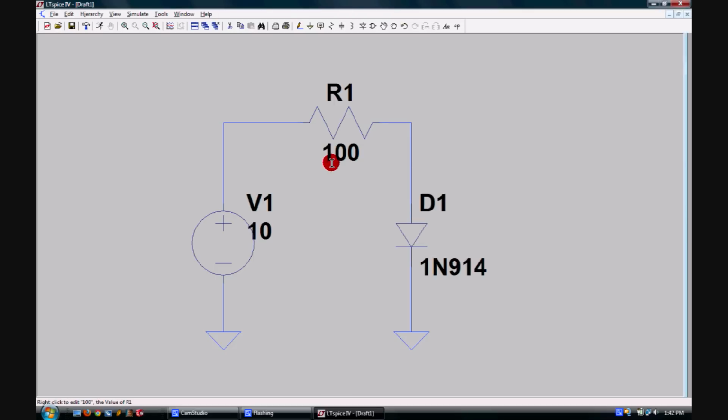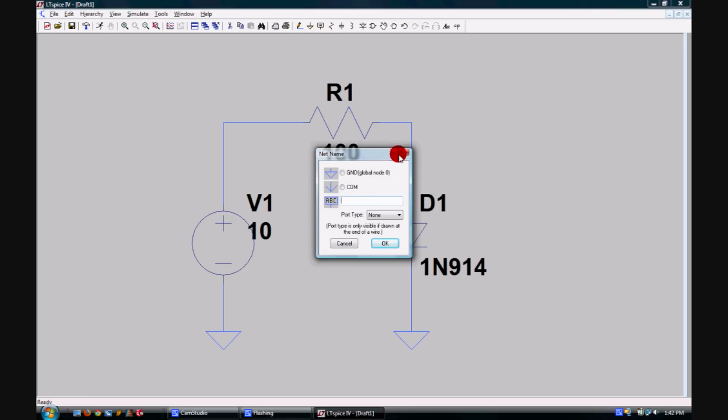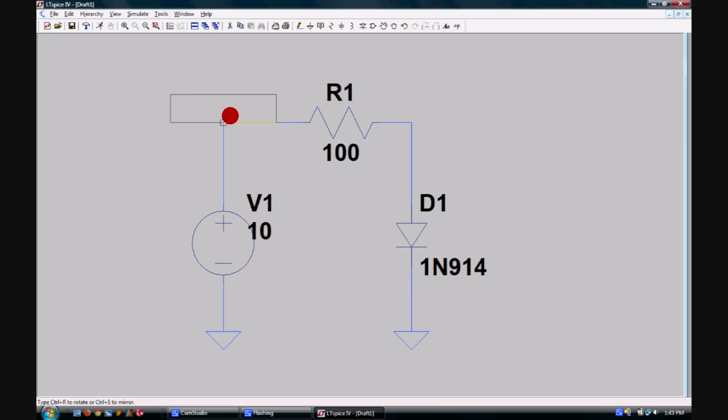No series resistance. Thing is, when we go to analyze our circuit, it's going to be really useful if we use labels for all the nodes. It doesn't really matter in this case, but for the pre-lab, it can definitely help you out. So click on this net label button and type whatever you want to type. So in this case, this is a resistor node, so we can do resistor 1. Click OK. And notice that when I connect it to a wire, the wire turns yellow. So that wire, that node, will now be labeled as resistor 1.